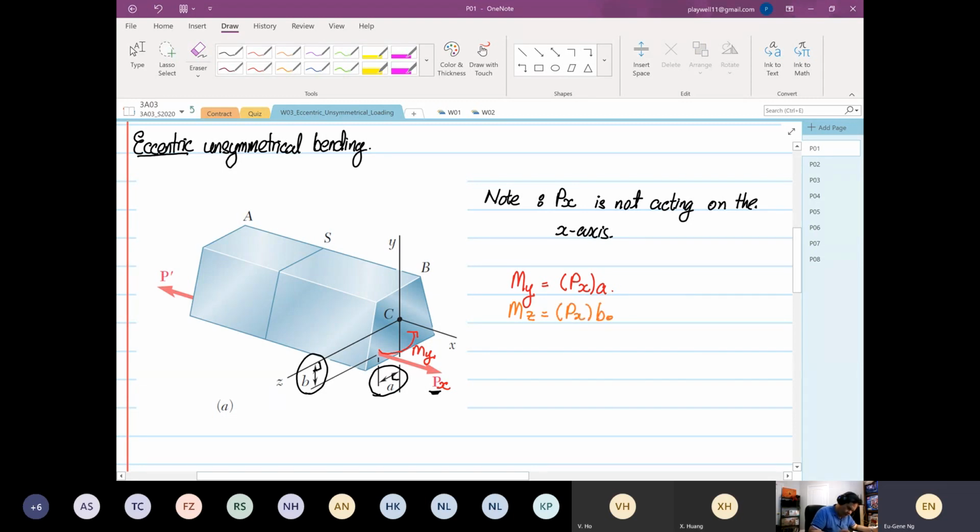So this is again our moment about Z. Our moment about Z over here on top is still under compression. Below the arrow is tensile. And for the moment about Y, the head is compression and the tail end is tensile based on color. So our analysis did not change, right?